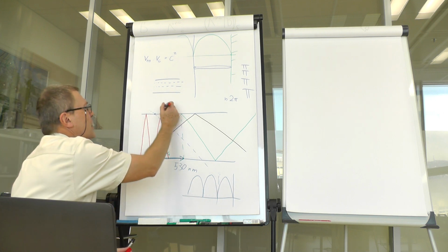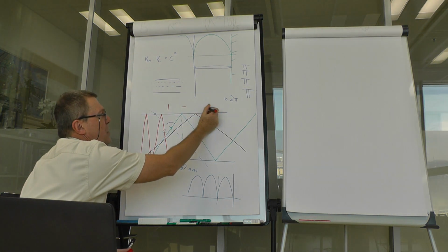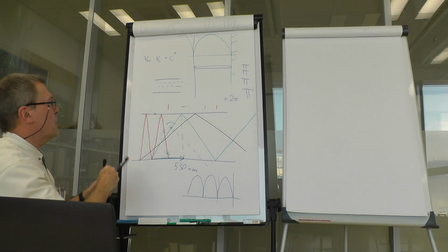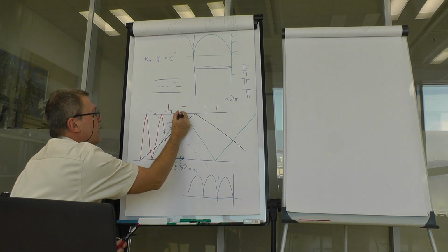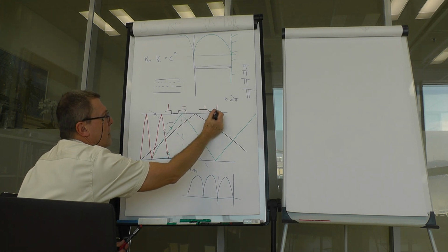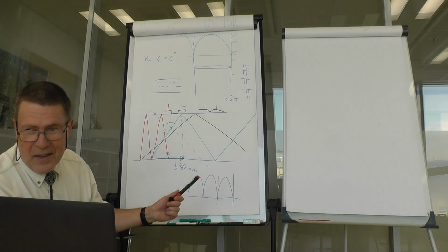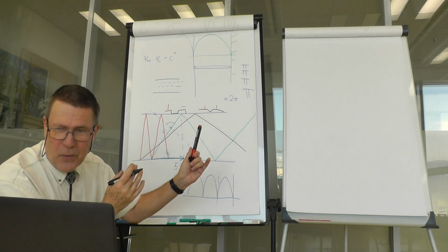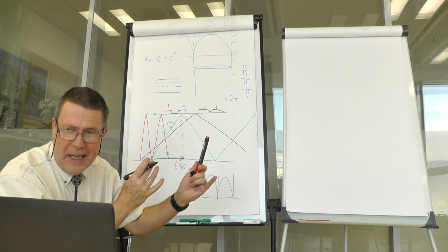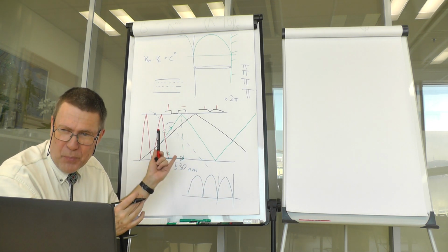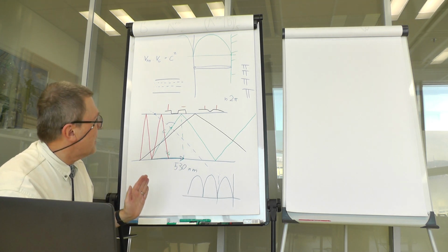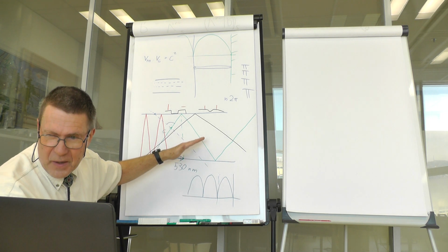If you send just one pulse and it produces two pulses at the output, it seems fancy, but what if you send a sequence of pulses? The first and the second wave would mix at the output, so that you would not be able to reconstruct the signal at the input. This is called dispersion, and it's typical for multimode propagation.